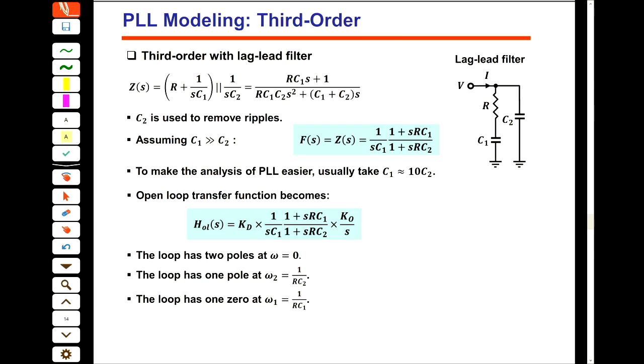Yeah. I wasn't sure about the collector part, how it will reflect. Yes, now I definitely understand. Actually the intention of this question is that when we have this C mu, then the input impedance of this structure is dependent on what we put in the collector. Because in the low frequency small signal model, the input impedance does not change much from here. Okay. Thank you so much.